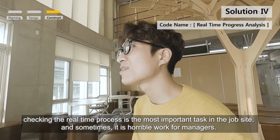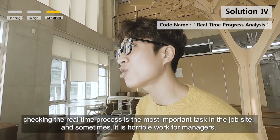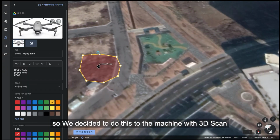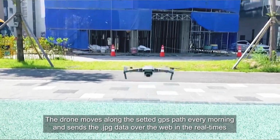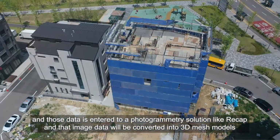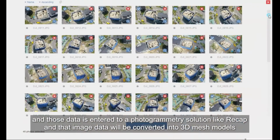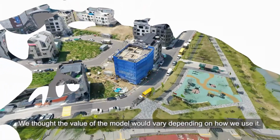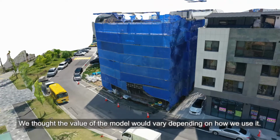Checking the real-time process is the most important task in the job site, and sometimes it is horrible work for managers. So we decided to leave this work to the machine with 3D scan. The drone moves along the set GPS path every morning and sends the JPG data to the web in real time. Those data are entered into a photogrammetry solution like ReCap, and the image data will be converted into a 3D mesh model. We thought the value of the model would vary depending on how we use it.